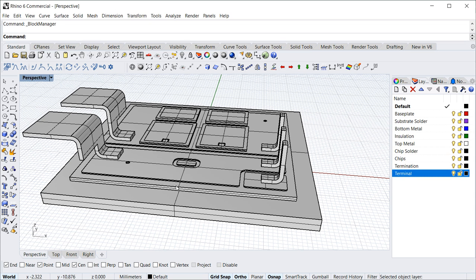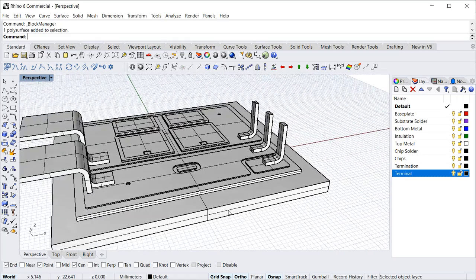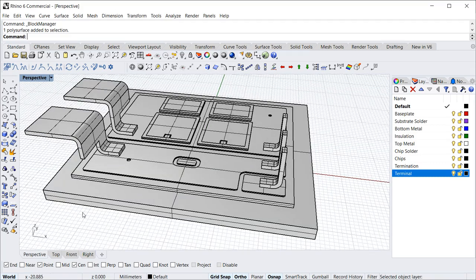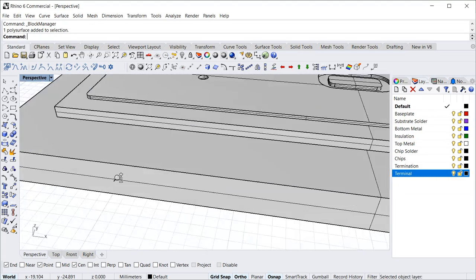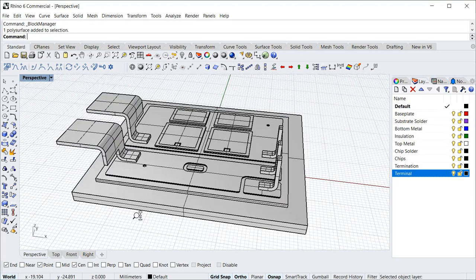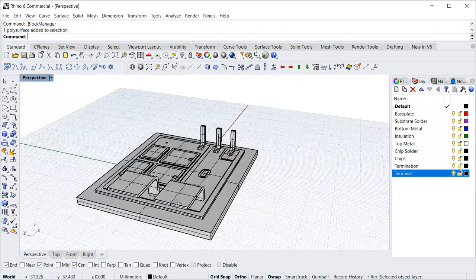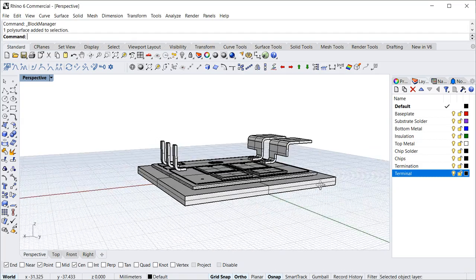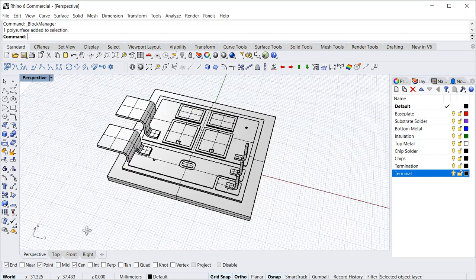Okay, we can now with left click. Okay, I didn't tell you how to navigate the view, I just did it. So with right click you can rotate, with shift and right click you can move your part, with control and right click you can zoom. You can also zoom using the mouse wheel, and when rotating it always rotates around the Z axis of your coordinate system. Maybe you're not used to that.